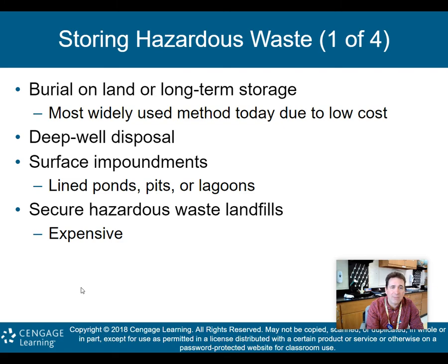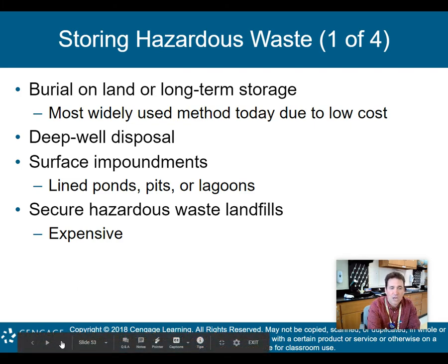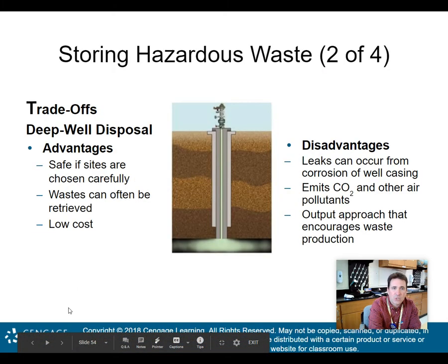You've got surface impoundments. These are lined ponds, pits, or lagoons. What we mean by lined is lined on the bottom with something that is not permeable to water, maybe clay, or some kind of fabric or plastics that we have created. Basically, the key is you don't want hazardous wastewater leaching down into the groundwater, so you need these lined ponds, pits, or lagoons that can help trap that water. Secure hazardous waste landfills, however, are expensive. This is one of the main issues we come across when we deal with storing hazardous waste.